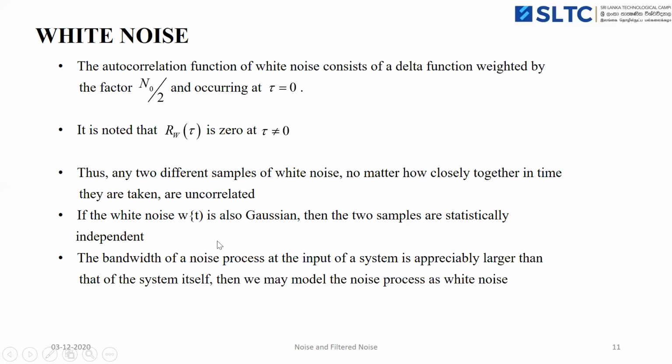Another important point about white noise: the bandwidth of the noise process at the input of the system is appreciably larger than that of the system itself. Then we can model the noise process as white noise, which means that when the bandwidth of the input noise is larger than the system bandwidth, we can model the noise as white noise.